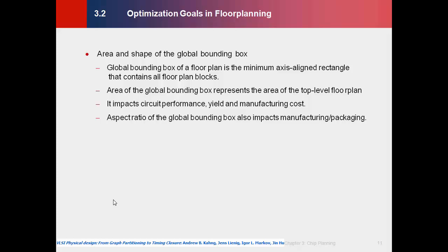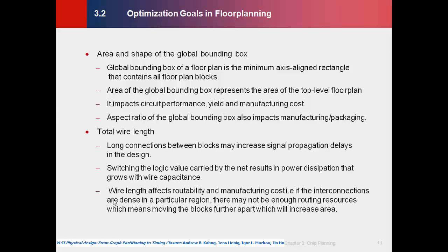And in certain cases, the aspect ratio, the width by height of the global bounding box, also impacts manufacturing and packaging, especially if the packaging technology is available in a fixed pattern. So you might have to orient your top level floor plan to suit your packaging at the end of the design. So why are we so concerned about the wire length?